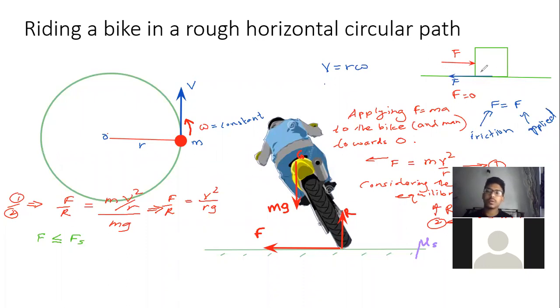Now I keep increasing. Now 2 Newton, still the box is not moving. Imagine you have a table in your school classroom and you are pushing it. You are increasing your force, still not moving. So you keep gradually increasing, but at a certain value, it suddenly slides. That is the moment where the equilibrium breaks, as it just passed the maximum friction value. So this friction can have a maximum value, F maximum, which is what we call Fs, the static friction.